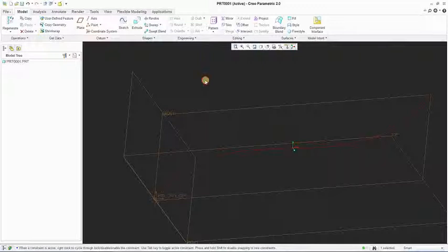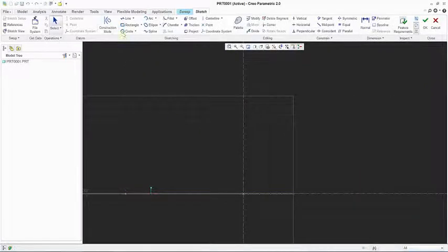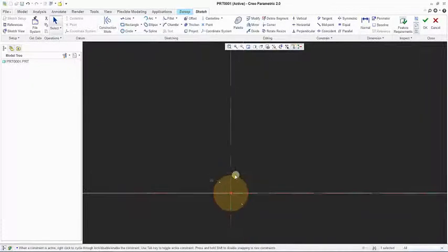Now what happens in this place is I'm going to do sweep only. I'm going to take a variable option only. I'm going to create a surface. Basic sweep command I'm going to execute, nothing else. I go into the sketch. Let's say I say circle, I'm going to go into the circle has already been created, let's say somewhere around 100.